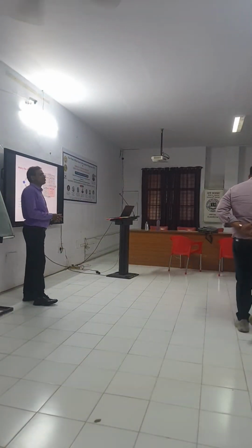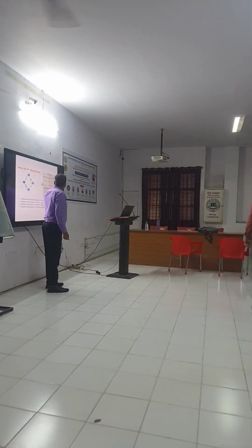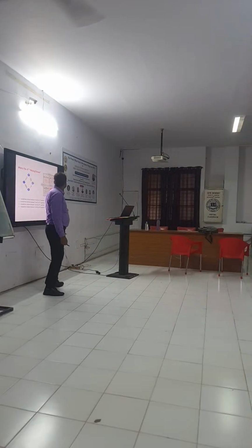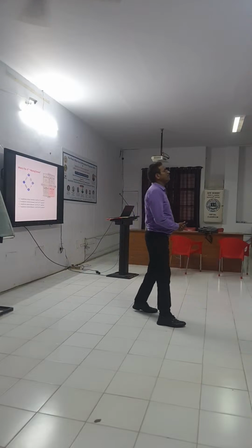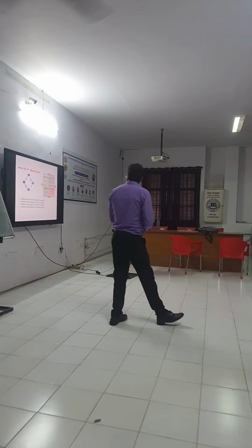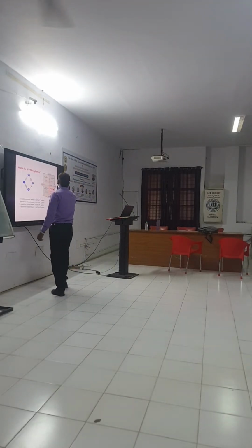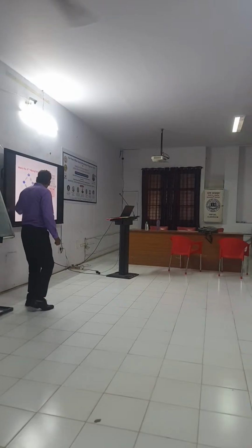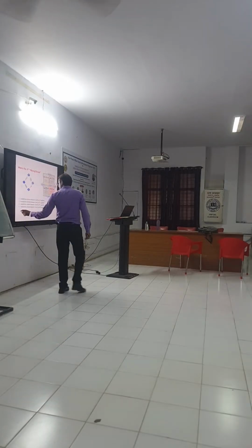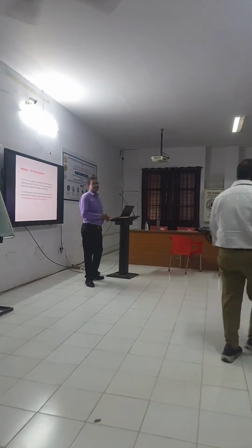Charge and flux. That was invented by Leon Chua. It is the relation between charge and flux. The rate of change of flux per unit charge is the memory state, so d phi equals M dq. This M is the memristance, the memory state. That was the missing one, written in the same way. Now it is the memristor.